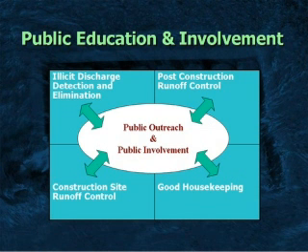So, for instance, in illicit discharge, we've pointed out that a key way to make that program successful is to let your citizens be your eyes and ears. If there's midnight dumping of chemicals and things like that, your citizens are your best bet as to the people who will see that first. And so if you establish some kind of phone number or hotline where they can call in, and they understand that this is indeed a problem, that somebody is dumping something down a storm drain, you'll have a much more effective program. The same thing in post-construction: educating developers and builders about low-impact development techniques and the kind of good permanent stormwater controls that we can put in place will make that minimum measure much more effective.